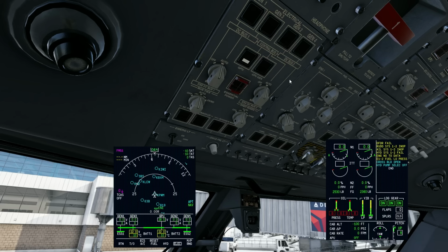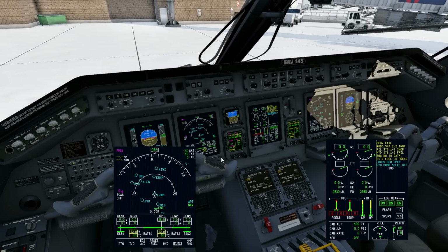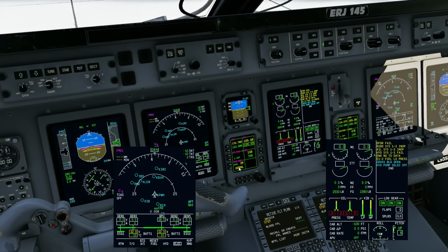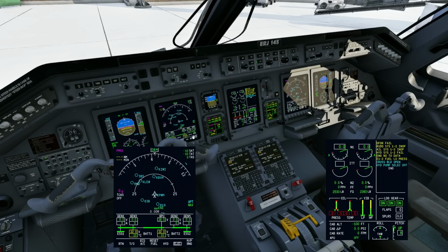If this were to happen to you, the aircraft is designed to put the airplane in essential power mode, which would power essentially the middle panel here. You would have your standby instrument, your radio management units on both sides, and you would have your EICAS. And that's what you get. PFDs go dead, FMSs go dead. You're in an electrical emergency, right? You're not flying an RNAV arrival. You're asking for emergency vectors to the nearest airport, maybe tuning up a VOR. Well, if this happens on its own, great. It puts the plane in a power saving mode, and that gives you about 40 minutes of battery life.